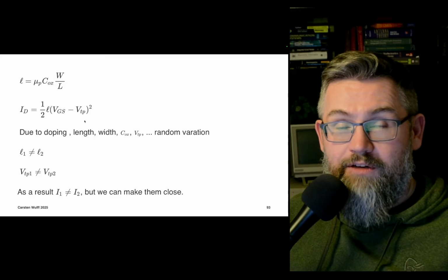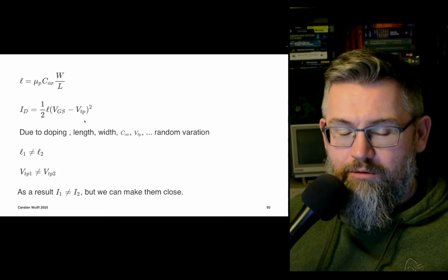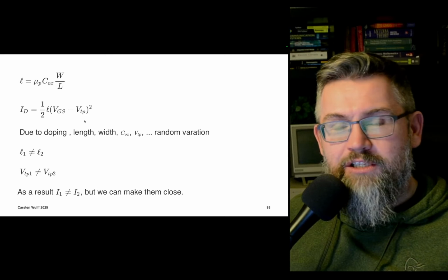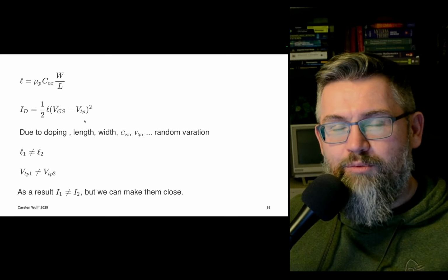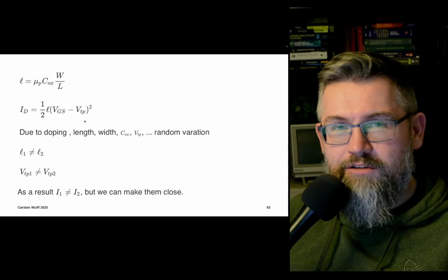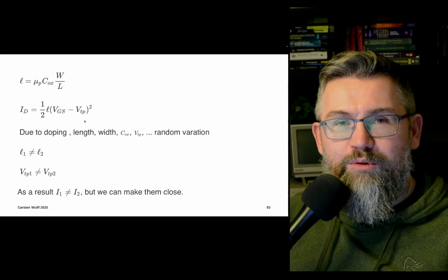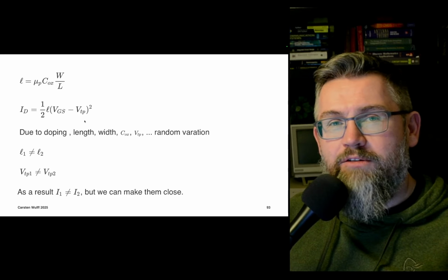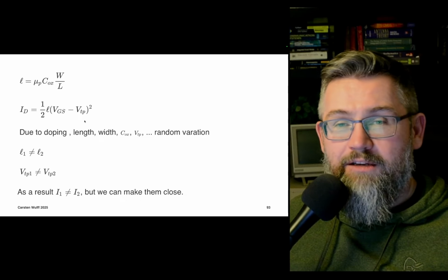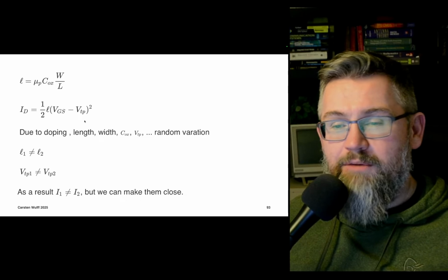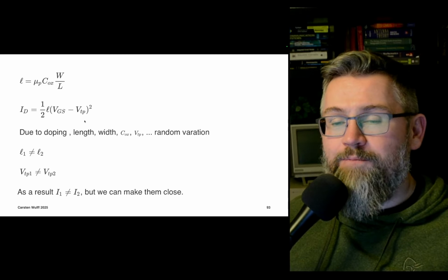We do have quite fantastic mathematics in order to improve that by using what's called pre-distortion, where you actually calculate the interference patterns of the light before you expose the wafers through the mask, so that you pre-compute, because we know how light works, the patterns that would be correct in order to get the patterns that we want on the wafer. But even that has a limit, and we end up with double patterning and triple patterning, putting multiple masks for the same layer and so on. And well, yes, we have extreme ultraviolet, but that's insanely difficult.